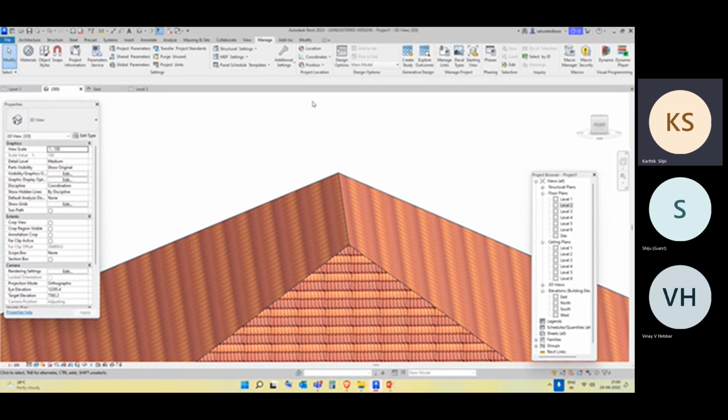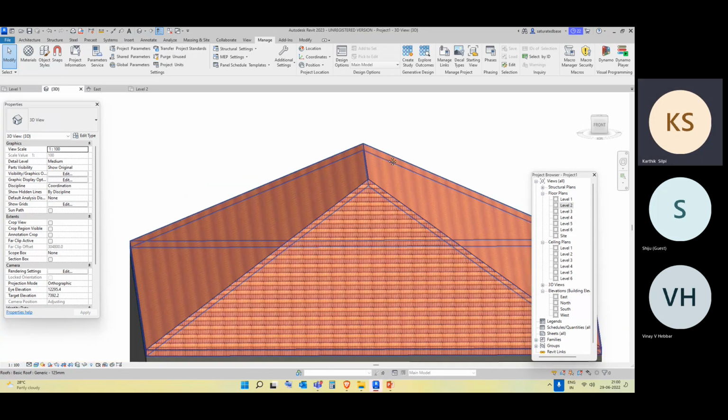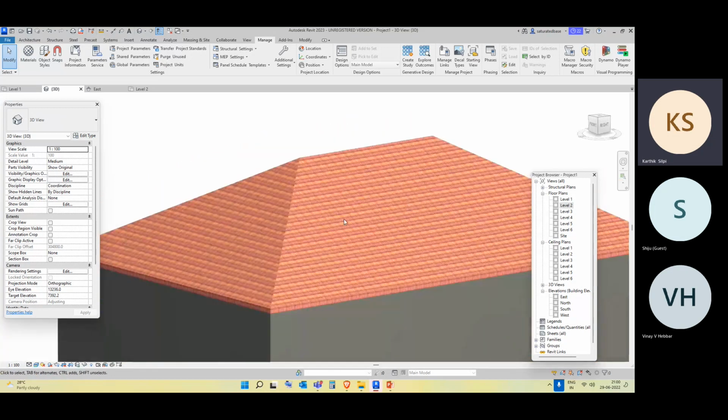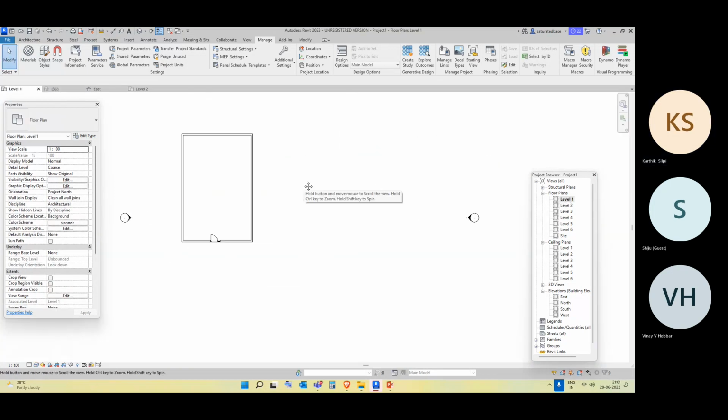The whole Revit model can be sent to rendering engines such as V-Ray and all. There also you can apply render materials. The rendering output that you get in V-Ray is more accurate than the nominal rendering in Revit. But this is how you apply materials for any given object or element in Revit. You have to go to Manage and you have your materials catalog.